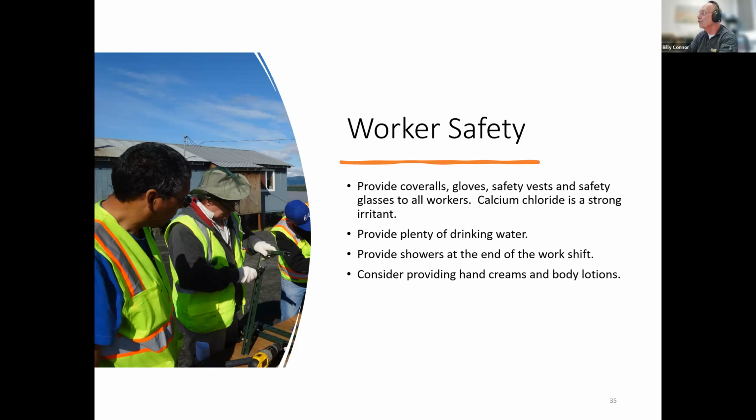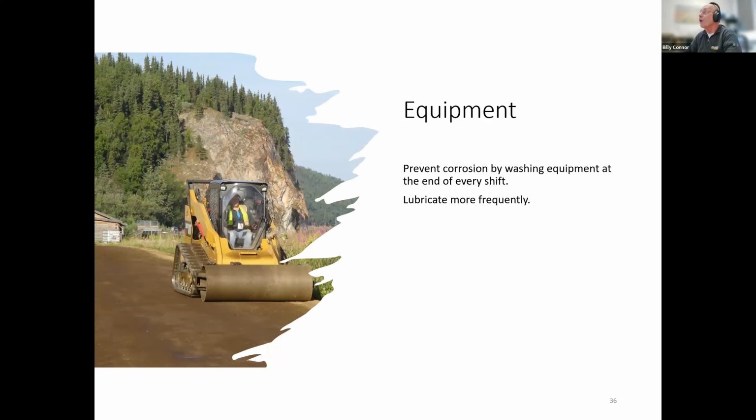But the real issue is the potential for it to get infected. We don't want that to happen. Equipment, you've really got to pay attention and take care of your equipment. You want to wash your equipment down, both inside and out, to the extent you can. At the end of every shift, don't leave it overnight because you'll come back to a rusted heap of iron, and you certainly don't want that. And then you probably should lubricate it more frequently than you would under normal conditions. So that's something to be thinking about as well.